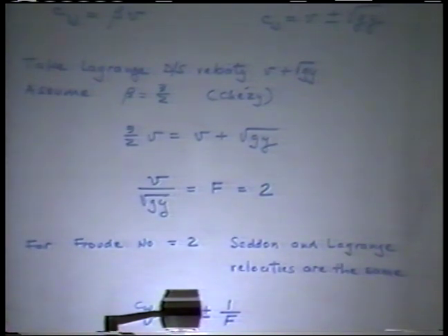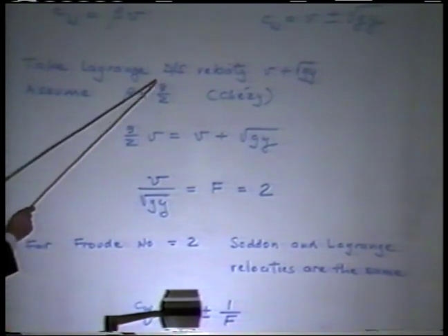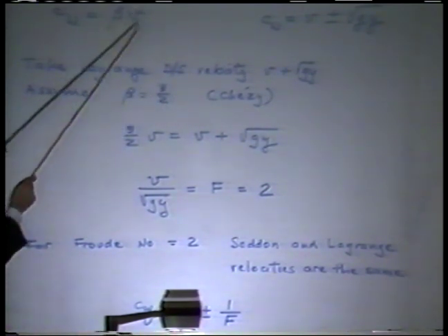And you can go back and repeat what I did for the Manning equation, and I ended up with a number which was 5/3, right? And you can do the same thing for the Chezy equation, and you're going to get a number that is 3/2. If I do that, then I can say that this is 3/2 and this is beta.